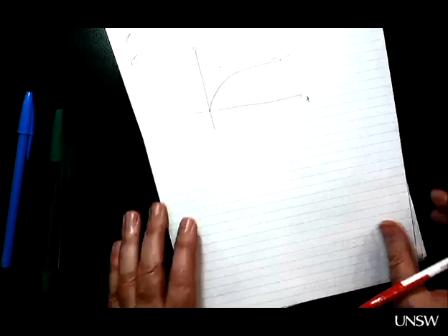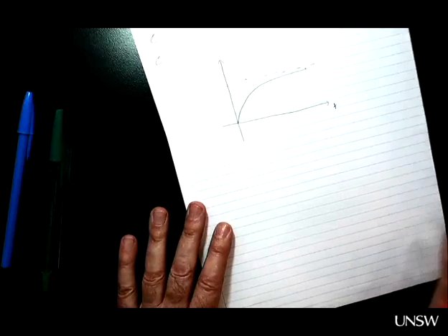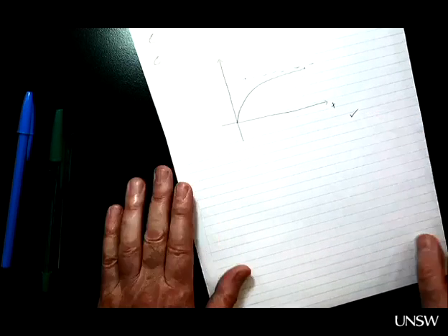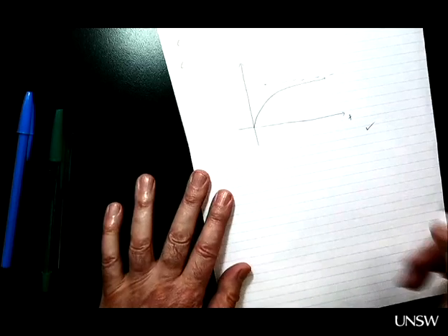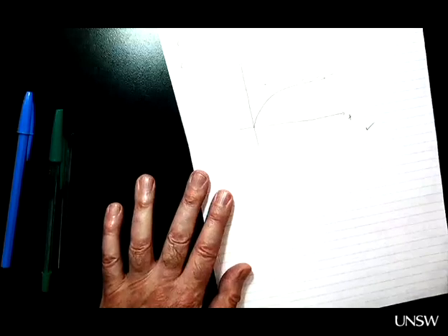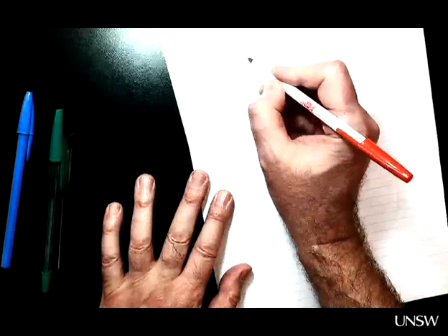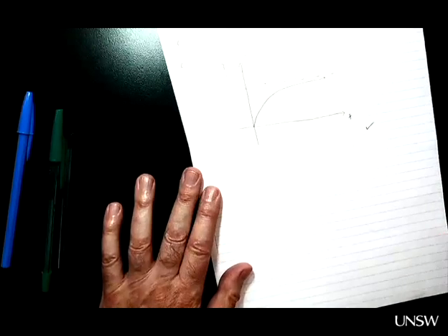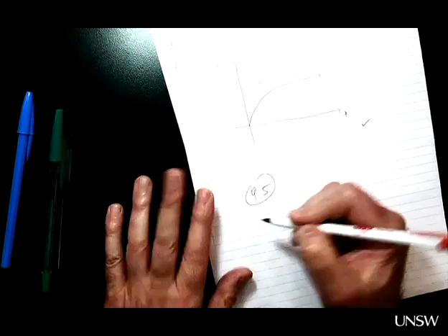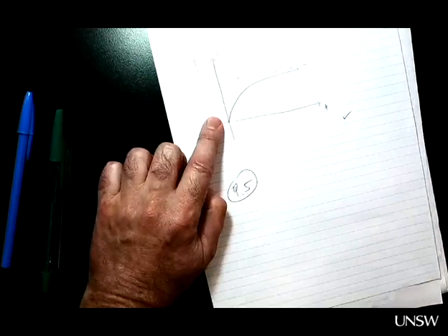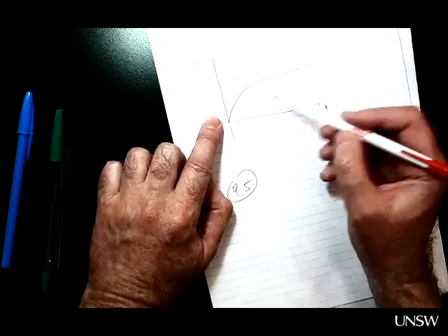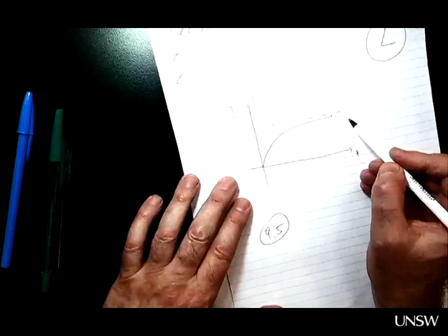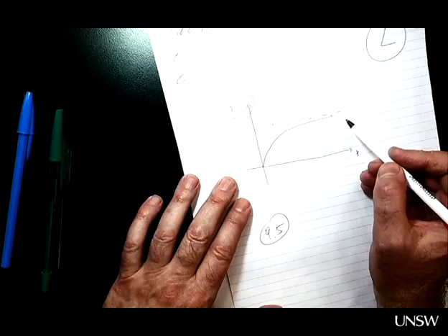Oh, this looks good. This is actually correct. However, yeah. You know, what is this? What is the function here? 9.5. Yeah, this is correct. The system is overdamped, so it must be exponential. And because it is a step response, it approaches a steady state value which is not 0. Okay, so this is a correct answer.